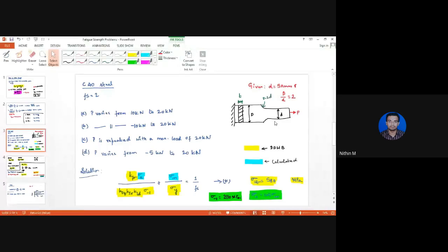Suppose I consider the maximum cross-sectional area, and I obtain the value of thickness by solving the problem. Based on this value of thickness, the component will be capable of withstanding the applied force at this particular region. But since there is less material present here to withstand the same force, the induced stress will exceed the allowable stress, thereby causing the component to fail.